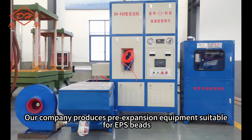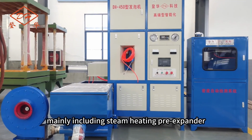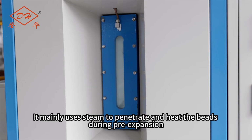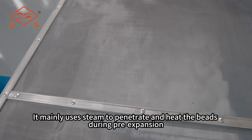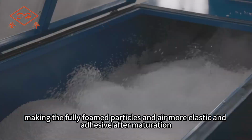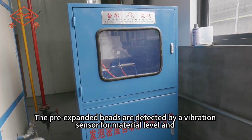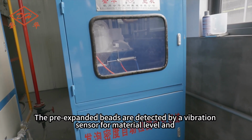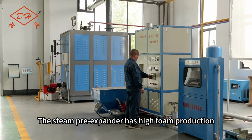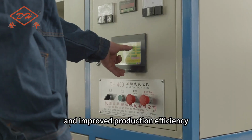Our company produces pre-expansion equipment suitable for EPS beads, mainly including steam heating pre-expander, which uses the most advanced PLC technology. It mainly uses steam to penetrate and heat the beads during pre-expansion, making the fully foamed particles and air more elastic and adhesive after maturation. The pre-expanded beads are detected by a vibration sensor for material level and automatically detected by a density detection system. The steam pre-expander has high foam production, low downtime, and improved production efficiency.